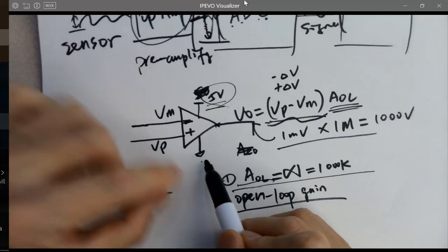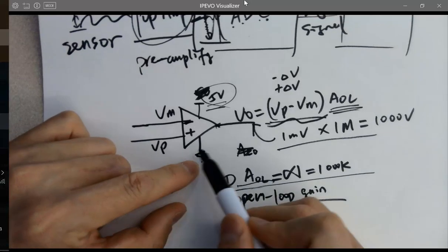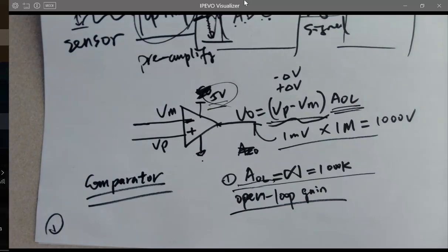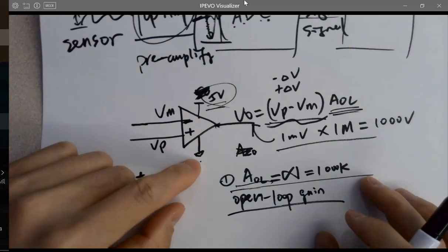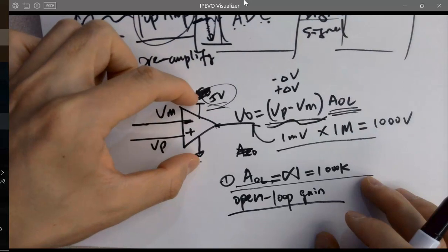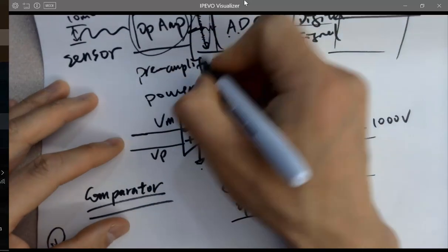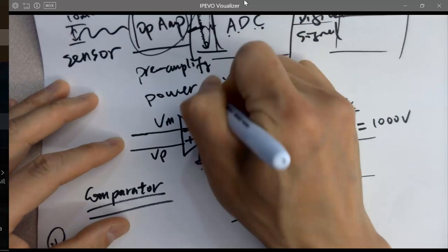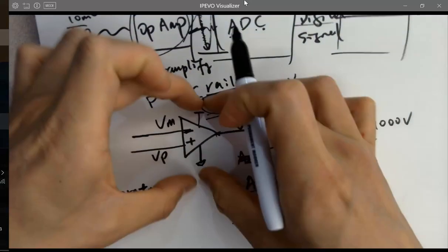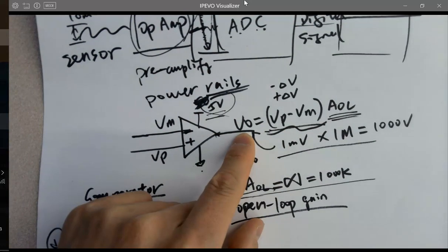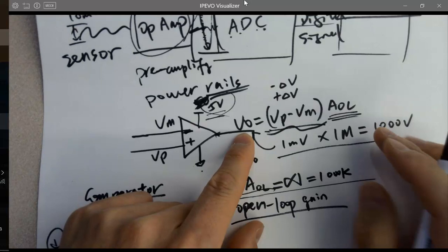You're asking why this supply sets the limit for VL. They are not connected. This is another thing that frustrates people. Keep in mind, you haven't designed that thing yet, so you don't understand what the top and bottom rails are. Just remember it, okay? The power supply's 2 power rails, the top and bottom rails, define the upper and lower limit of VL. Keep that in mind.